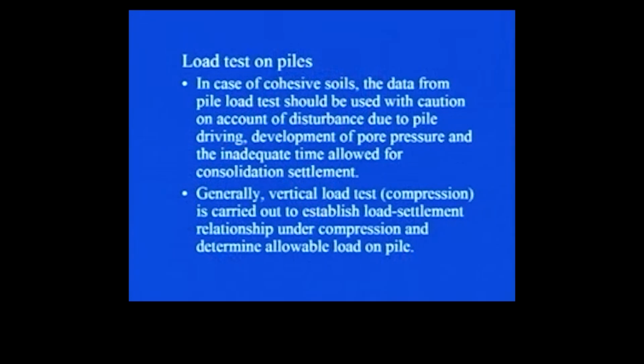Generally, vertical load tests, that is in compression, are carried out to establish the load settlement relationship under compression and then determine the allowable load on pile. You have studied this in case of shallow foundation also, how you can find out the ultimate load which any particular foundation can take with the help of the load settlement curve.